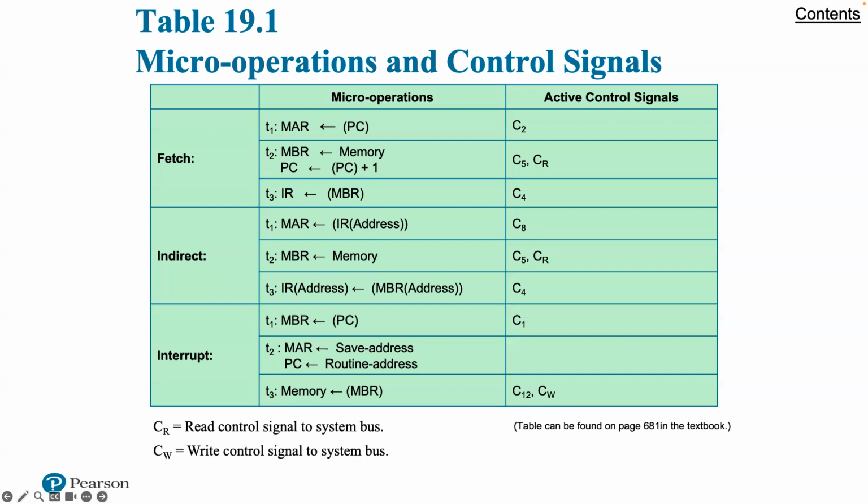It is worth pondering the minimal nature of the control unit. The control unit is the engine that runs the entire computer. It does this based only on knowledge of the instructions to be executed and the nature of the results of the arithmetic and logical operations, things like whether a result is positive, or if it has overflowed. It never gets to see the data being processed or the actual results produced. And it controls everything with a few control signals to points within the processor and a few control signals to the system bus.